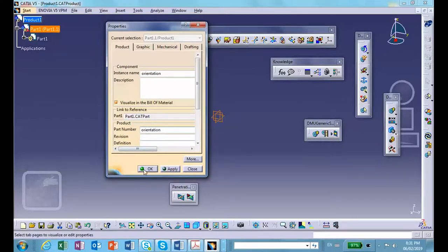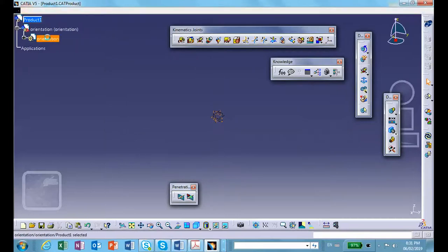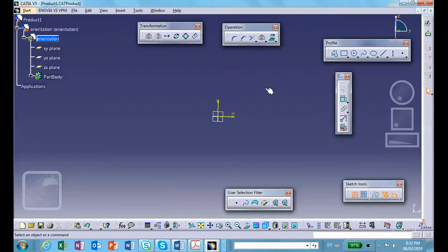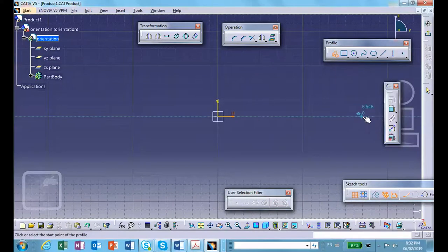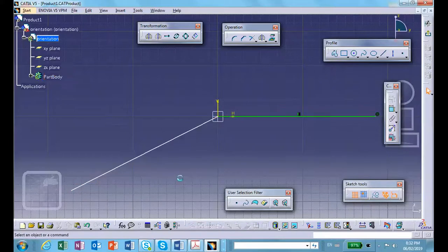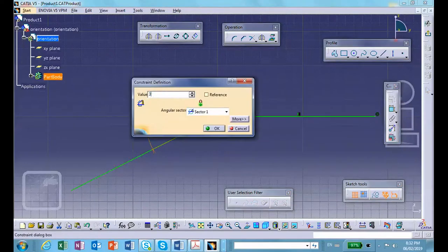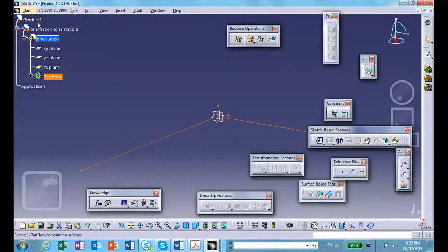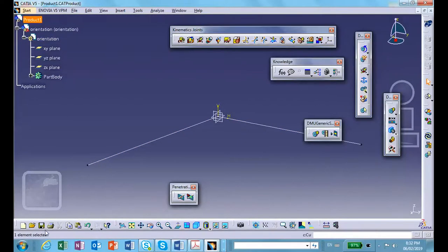Okay, let's make it. So double click on this. On a convenient plane, on that vertical plane, I will draw a broken line segment like so, where the angle between these two lines is 60 degrees. This is the angle of the two shafts, as you will see later. So let's make it 30 degrees. All right. Good. Exit, and obviously save. Save it.